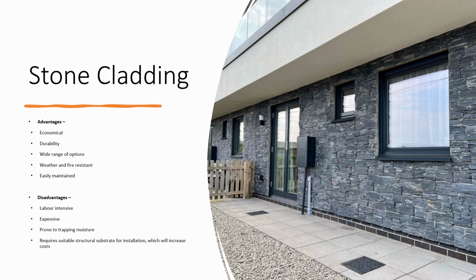The disadvantages are that it is labour intensive, it is expensive, it is also prone to trapping moisture, which can lead to bigger problems further down the line. It also requires a suitable structural substrate for installation, which will increase costs of the project.